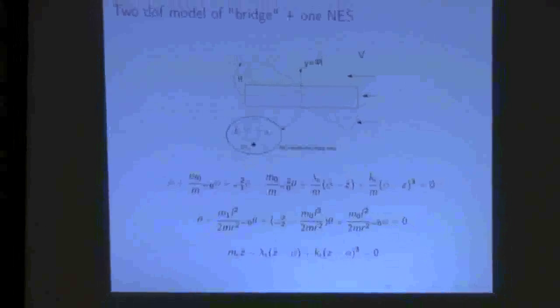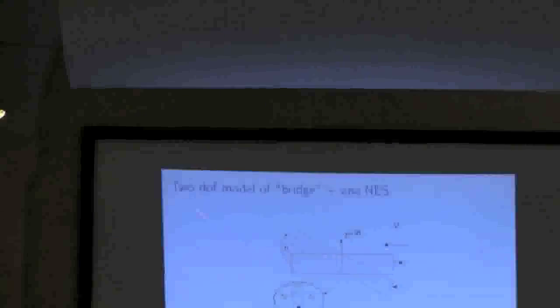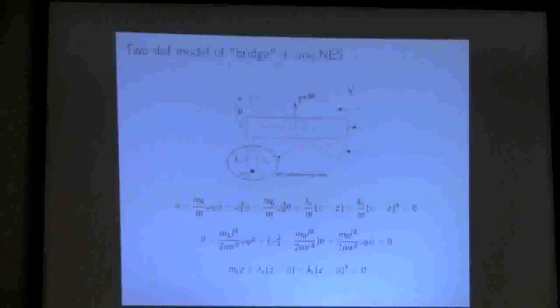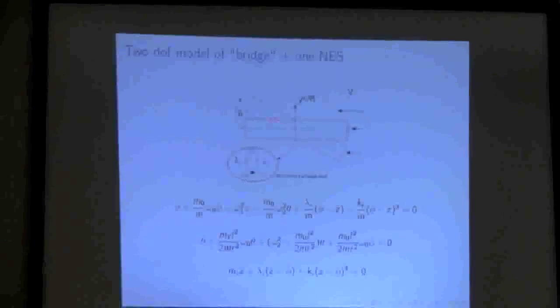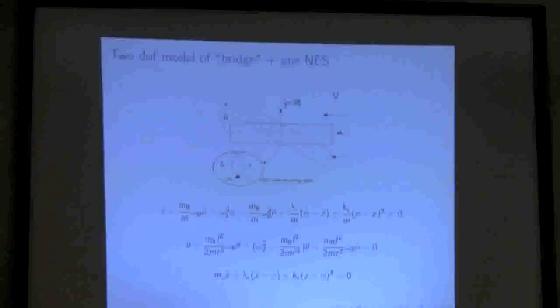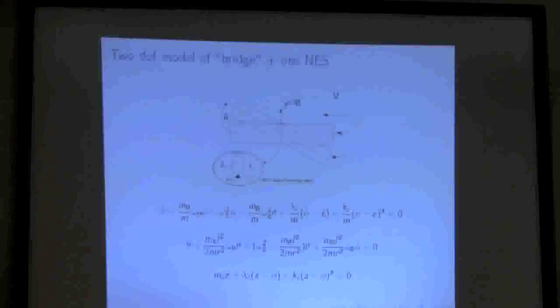that case. So it is a very simple model of a bridge. So it means we consider the deck of a bridge, and you could have the bending effect and rotation, but it's very academic because we consider, in fact, if lambda epsilon, k epsilon are 0, and if you suppress these equations, you see that you have a coupling between phi, that is the bending, and theta, that is the rotation angle.